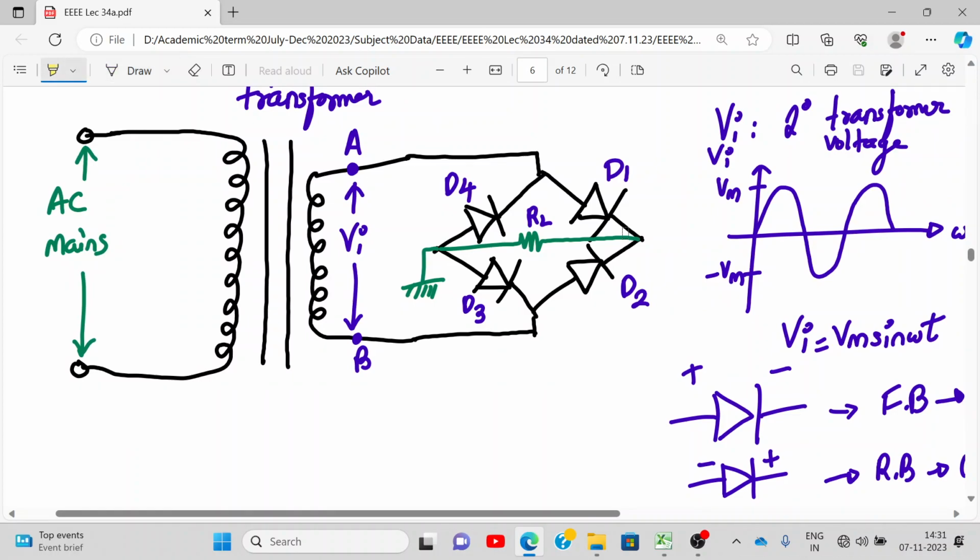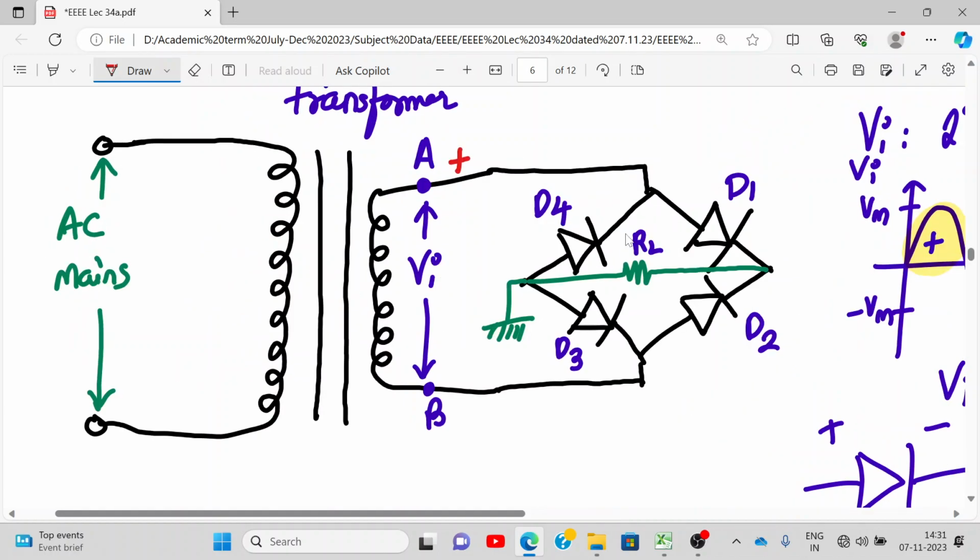Meaning I'm talking about this part. So for a positive half cycle of the input, listen very carefully. I'm using red color to explain now. Point A is positive with respect to B, correct? Now tell me which diodes are on. So this positive AC signal applies over here. Okay. Now will diode D4 be on? Because positive is over here, right? Here we are applying positive to the N terminal. So is it off or on? D4 is off. D1 is on? Yeah. So the signal proceeds to it.